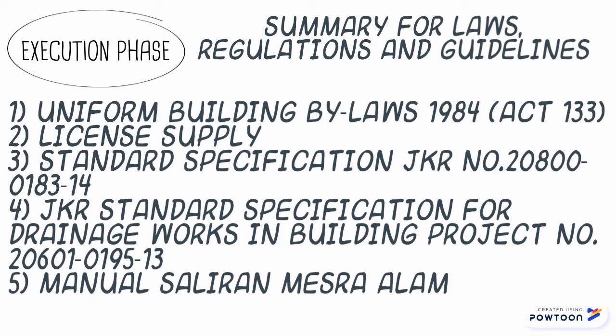Internal sanitary plumbing regulation is based on the British standard or European standard that can be found in JKR 2014 Section L, water reticulation, internal plumbing systems, and sanitary fittings. Firefighting. The standard requirement of firefighting can be found under the UBBL Part 8, Fire Alarm, Fire Detection, Fire Extinguishment, and Firefighting Access, Section 244. Mechanical ventilation can be found under UBBL Part 7, Fire Requirement on Section 200.